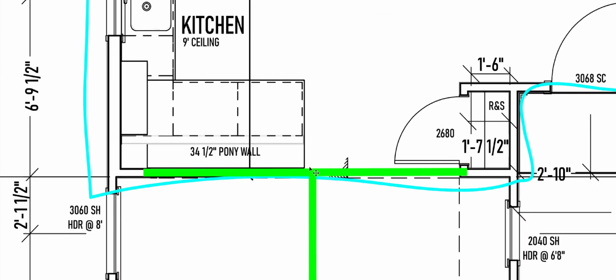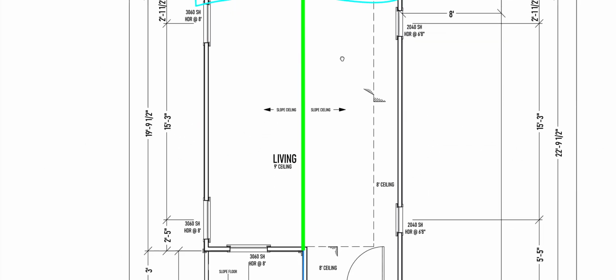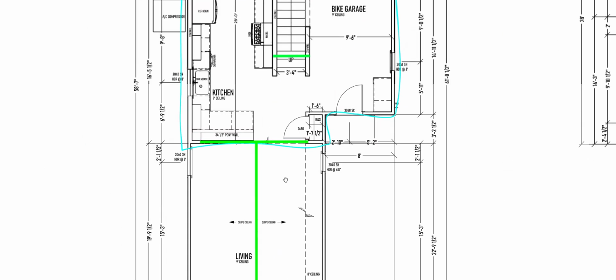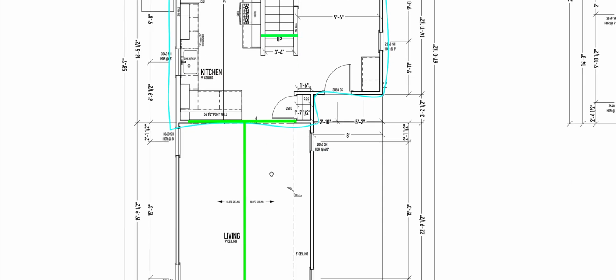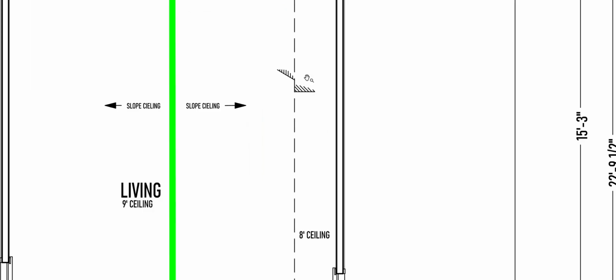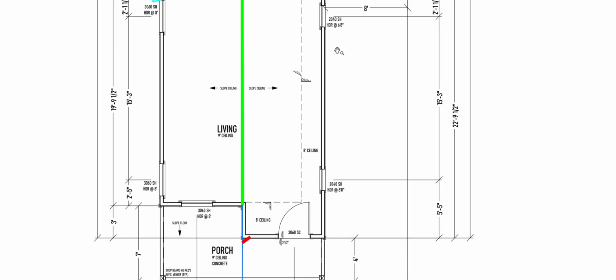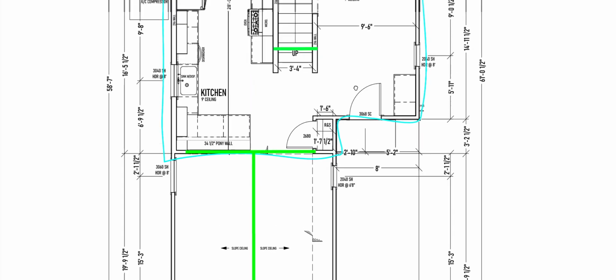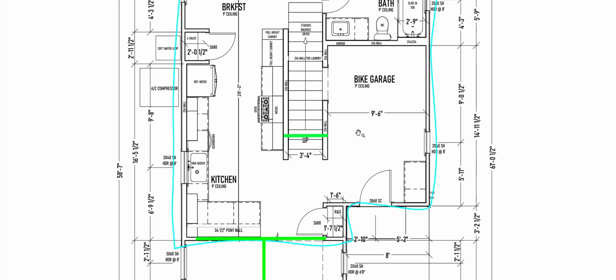So this one's going to sit on that one. So these are going to be some significant beams, most likely. But we just know that they're there. We'll calculate them later. So that holds up this whole roof. I'm happy with that. This is not extra crazy weight. This is just like blocking and stuff for the HVAC that's going to come through that chase, the empty part in the framing.